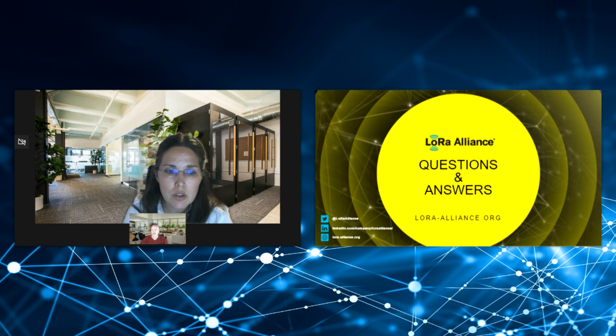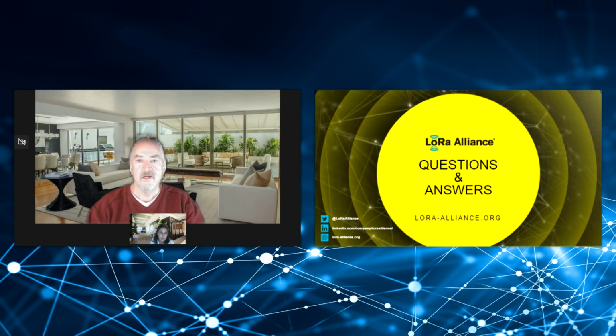At the end, once you select the test case and start running it, there is a window where you can see all the exchanged packages between the device and the LCTT. The first thing is to see if the connection to the gateway is there. So once you see push data, push ACK, this means the LCTT manages the connection to the gateway, and then you can start sending uplinks. I hope this is clear. So pretty much LCTT will tell you that it's set up correctly. Okay, good.